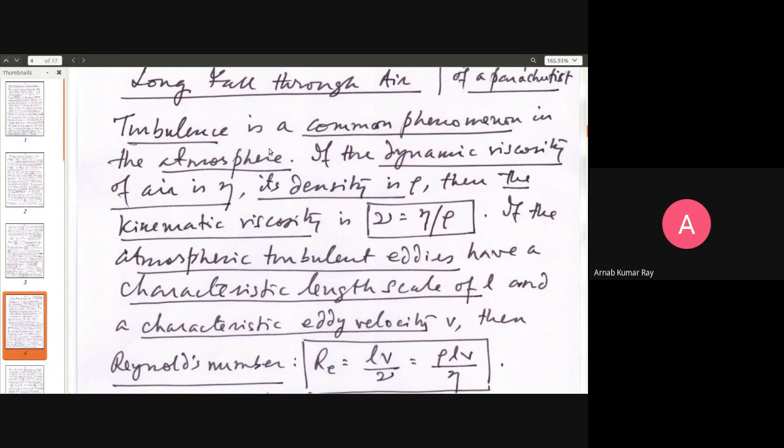And although the atmosphere is air, air doesn't have a very high viscosity of its own. However, turbulence will enhance that viscosity, in as much as turbulence enhances another inherent property of a fluid, namely diffusivity. I just gave you a common example of that. You want to dissolve sugar in coffee or tea, you create turbulence to make the dissolving process happen that much quicker.